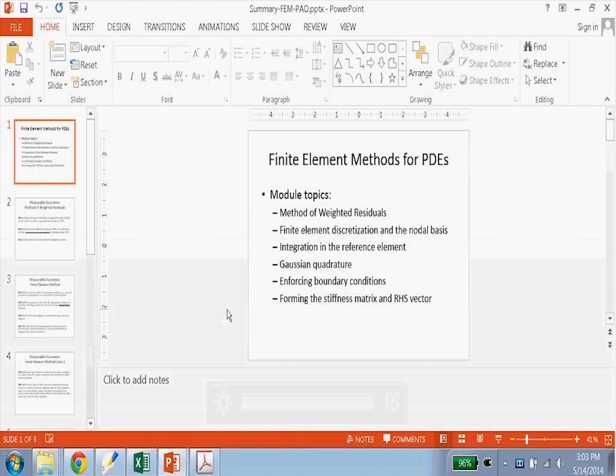and the main types of boundary conditions that we discussed were Dirichlet, where, remember, for a Dirichlet condition you specify, what do we specify? Yeah, the value of the unknown, the solution at a point. And for a Dirichlet condition, we are going to replace the weighted residual equation. We're going to look at forming the system in just a second, but we already said that setting each weighted residual equal to 0 gives us one row in our matrix system, right? One row corresponds to the equation Rj equals 0.